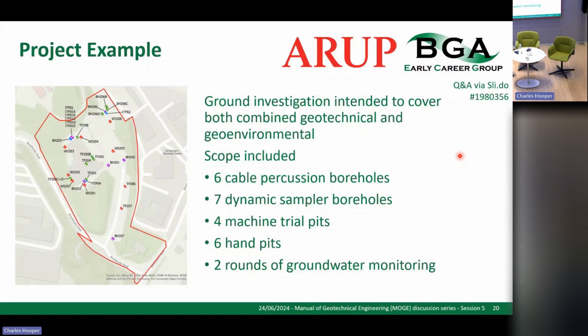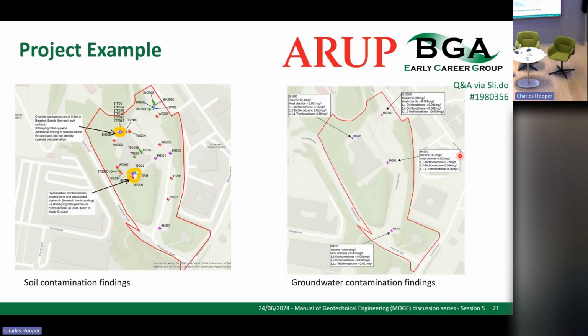A lot of the trial pits are actually to look at foundations, but the main ones around the wider site were focused around effectively looking at where we might find general coverage for contamination. We didn't have any point sources that we were looking at to investigate. So we have a combination of deep boreholes with installs, CP ones, to look at the water, slightly shallower window samples to 5 meters and a few trial pits to give a bit more coverage in the south area. And we were quite surprised, I'd say.